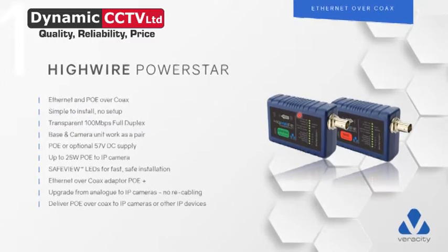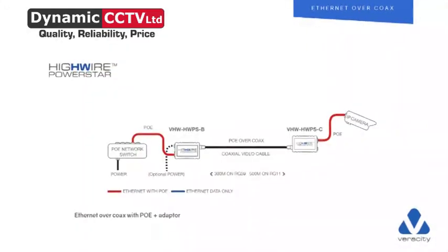This is very handy. You get to a lot of sites, all sites, you plug something into your coax. Well, is your coax working on a legacy site? Is it not working? The good thing about this is it'll tell you when you've got your link up, when you've connected them together. It'll also tell you if there's any data running over it. It'll tell you as well how many watts of power you've got at the bottom. So these could be 5, 10, 15, 20, 25 watt increments. That's critical. Sometimes you can spend hours and hours and hours and not actually realise that your cable wasn't working in the first place. It's a great test tool as well. Plug it in, it tells you it's there, tells you it's got power on it, how much PoE you've got at the end, which is always critical.